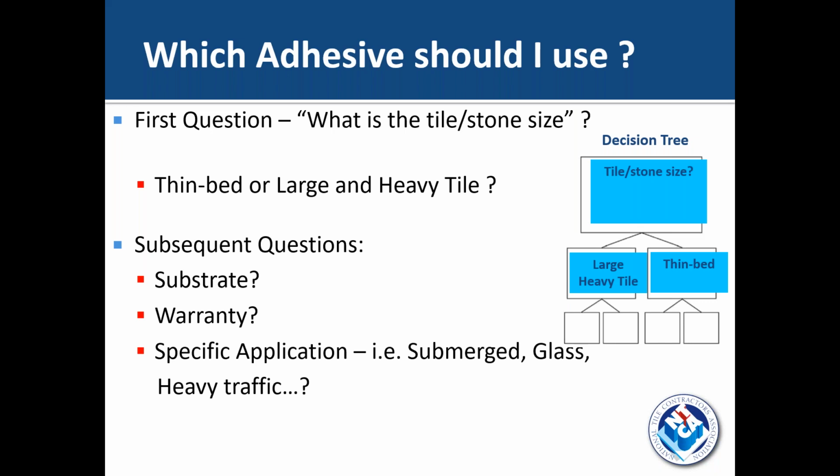Is bond strength important and how do we evaluate it? Well, bond strength is a component of all of the ANSI standards, so it's very important. And the highest bond strength is obviously with an ANSI A118.15 mortar. So when in doubt, I would say use an A118.15. That's going to give you the highest bond strength.